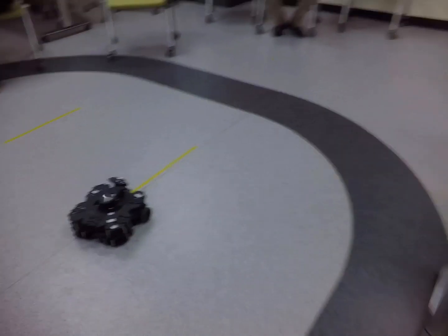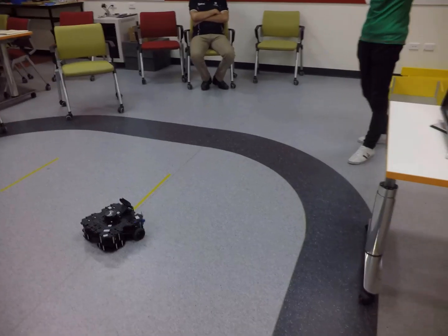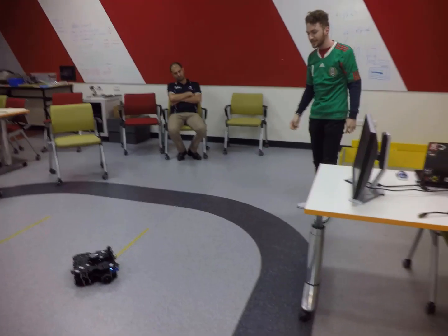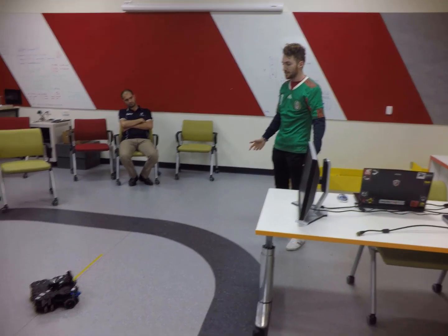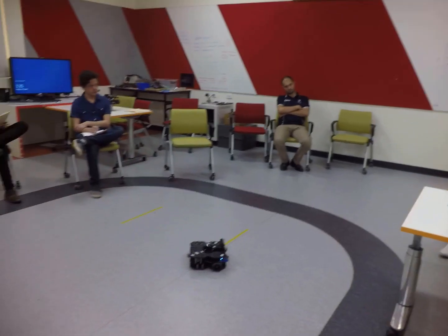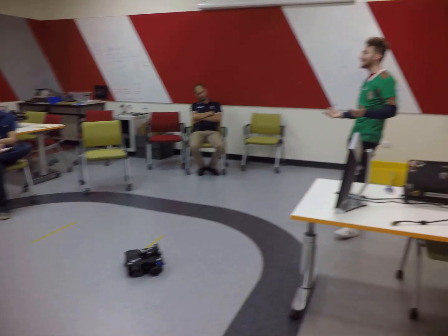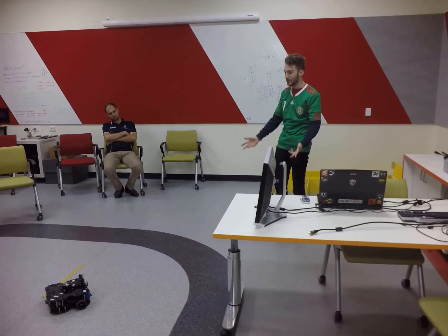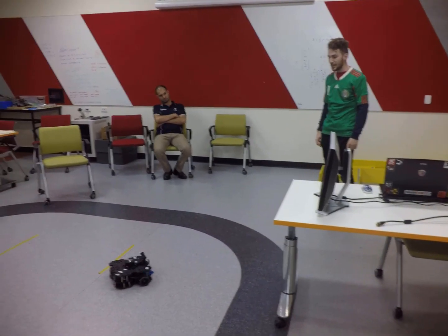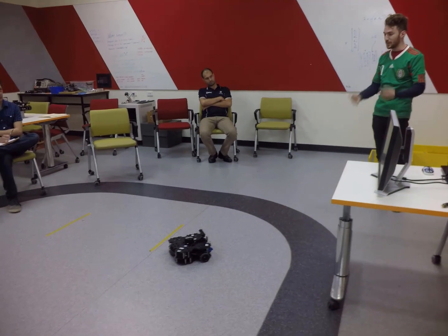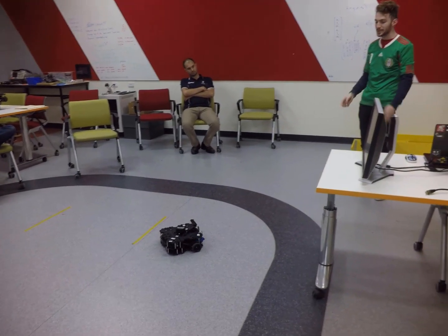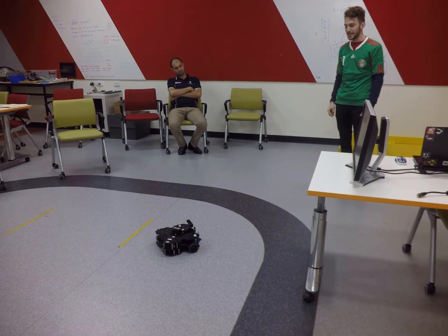I create my bounding box around every person, and then a new bounding box around the body area, basically to calculate how many pixels are green in that area, and if there is enough green above the threshold, it will start trying to follow me based on where I'm standing. So the angular velocity is based on the midpoint of that bounding box. I just use a linear relationship between that.